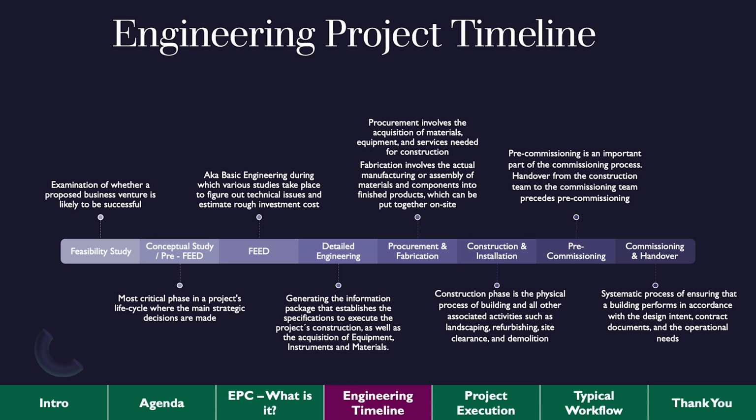Right. And pretty much all the data sheets for all the different equipment are supplied by process data: temperatures, flows, pressures, etc. Now the other engineering disciplines, like mechanical, electrical, and civil engineering, will be able to complete it and send all these data sheets for every single piece of equipment to procurement, to get out there and start picking which vendors can provide that equipment, and of course your selection is then going to be constrained by the cost.